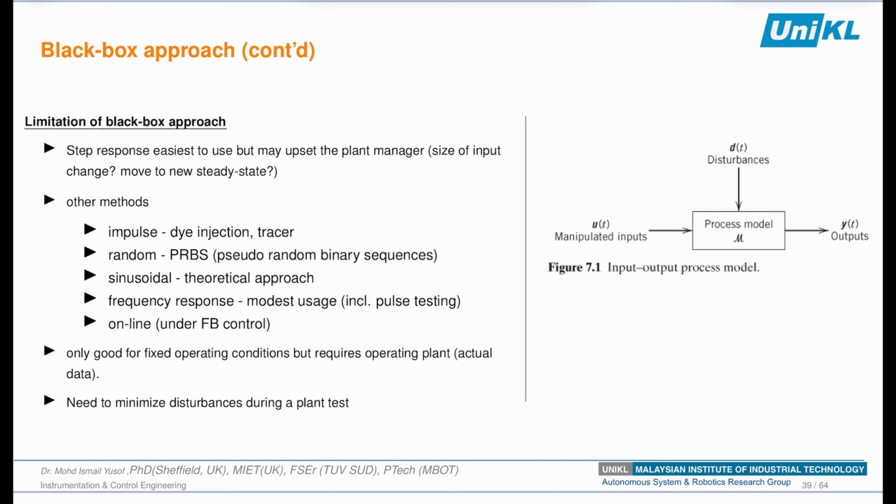One of the limitations is because of the step response. Even though the step response is the easiest to use, it may upset the plant manager. This is due to the size of the input change, as the step changes from minimum to maximum. That is what we call a step input.